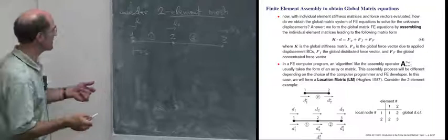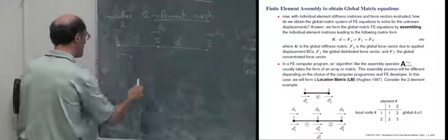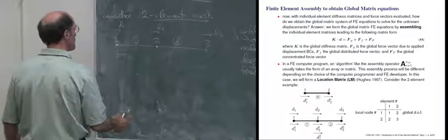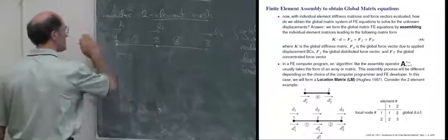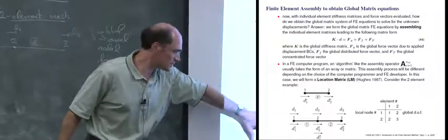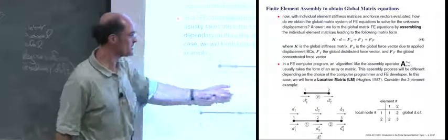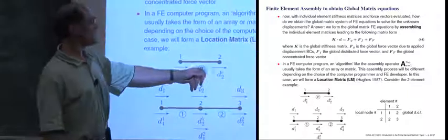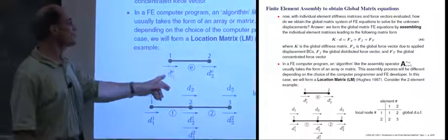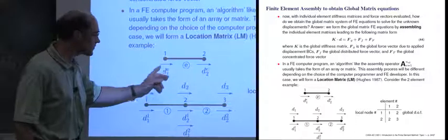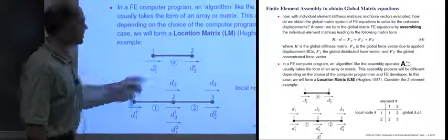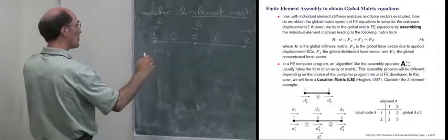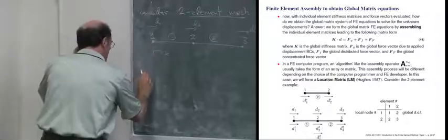Now remember our element perspective. So our element perspective is we take out one of these elements here, let's say element 1, or so this is the global mesh. So the element is here. I'm not going to redraw it, but I will look at just one of the elements. So remember, from our element perspective, we have an element, generic element E. We have these generic local element degrees of freedom 1 and 2, local nodes 1 and 2, like this. So if we apply that analogy or that concept to element 1, so this is the global perspective here. So then the local,